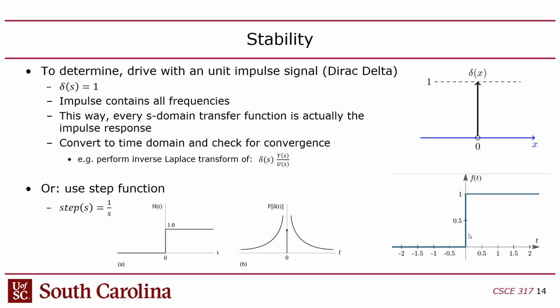Okay, so this is kind of esoteric, but bear with me here. I mentioned the impulse response, right? So what does that mean? It means that we're going to take the impulse and marry it to the plant, and then we're going to run it. Or actually, not run it, but define it as a combined system, impulse and plant together, and then you can check for poles, for instance, right?